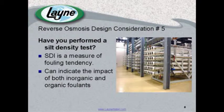The SDI is a very good proxy for what types of fouling, what level of fouling you're going to have in your reverse osmosis system. It might dictate some further pretreatment ahead of your reverse osmosis system, or dictate at the very least what type of cleaning regimen is going to need to be in place. So there's 5 quick considerations for you.